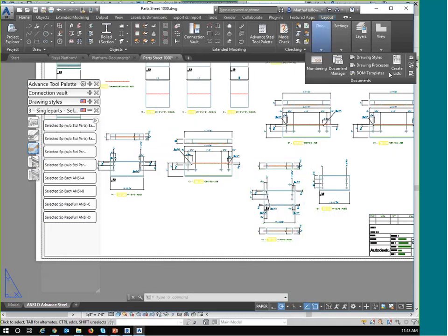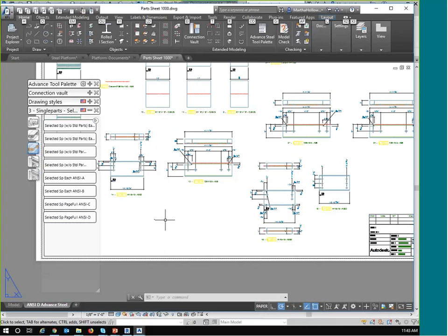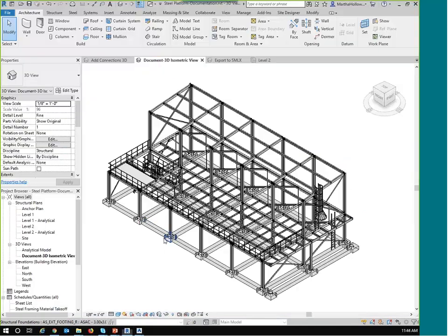You'll also notice that in here, like I said, we can do the bill of materials. You can also do NC files, so putting it out to the NC module. You can do DXF, and some fabricating equipment uses the DXF. So you can do those things as well. And then this is the NC setting. So if you are using NC, you can set it all up so that it can go straight to fabrication. Very, very, very powerful tools.